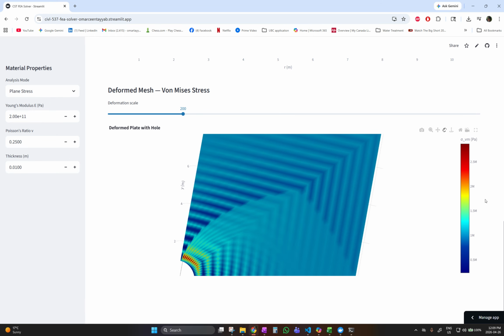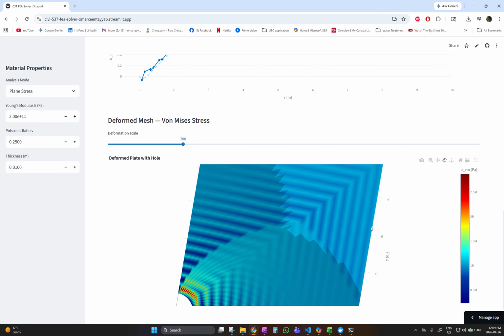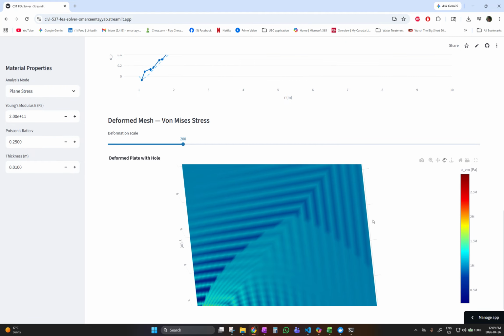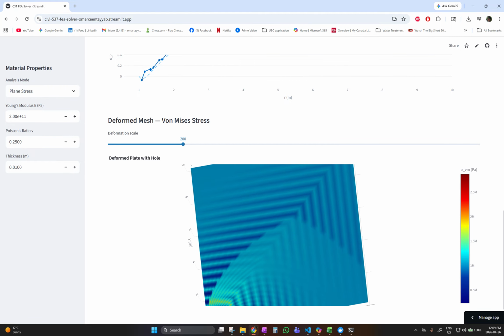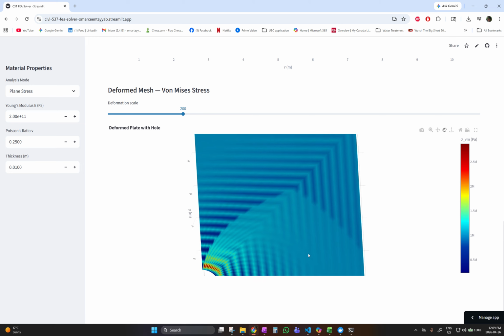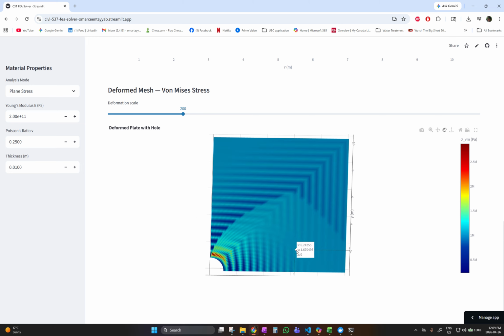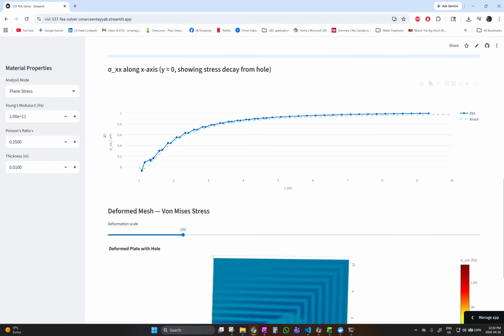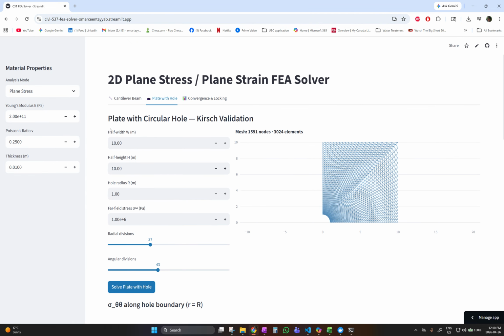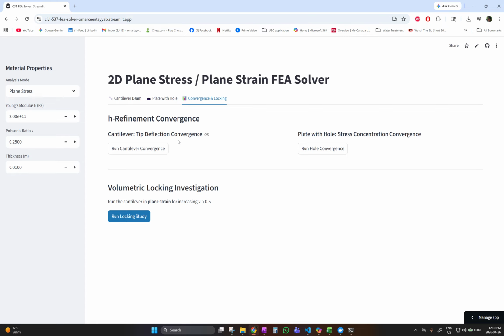I feel like the way I did the mesh this time was way better compared to my previous MATLAB solution that I just showed you. In the MATLAB solution, I set the Young's modulus inside the hole to be 0, rather than meshing the hole accurately. Here, I actually made a good attempt at meshing the hole, so this looks way better. Yeah, that's really all I want to talk about. I'll leave that for the Viva, the in-person call.